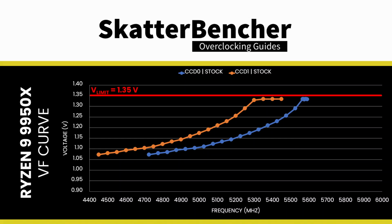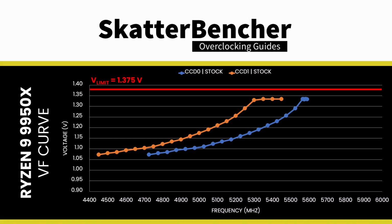We also notice that the maximum allowed voltage is 1.35 volt when all cores are active. We can increase this to 1.375 volt by setting a 10x scalar. The Precision Boost 2 algorithm utilizes the VF curve to find what's the maximum allowed frequency at 1.375 volt. With the default curve, that's 5600 MHz for CCD0 and 5450 MHz for CCD1. However, as I showed a little earlier, we can use the Fmax Boost Override tool to increase the Fmax limit by another 200 MHz.